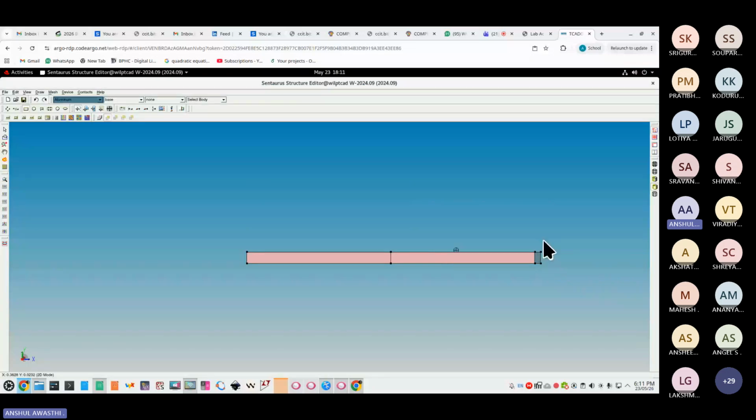Now here you have to just imagine the coordinate system. If you can imagine this, then you can draw any device. Now I have started from 0 in the x-axis. That means 10 nanometers before will be minus 0.010, because the starting point is 0. So I want to go 10 nanometers before my starting point. So for placing the contact, I'll just draw a rectangle anywhere.